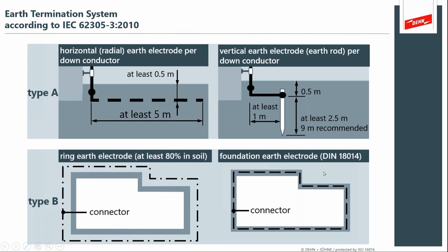So you often hear the term the Ufer ground, which is essentially using the concrete and the embedded rebar in the concrete as an electrode, and they all work correctly if in fact bonded and created. And we'll see a few images of this as well.